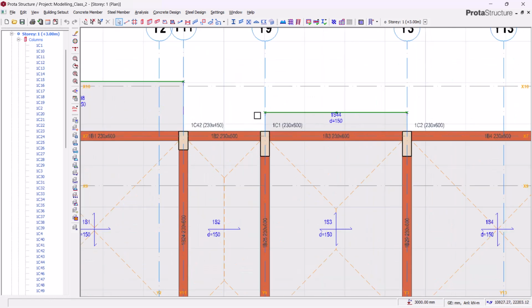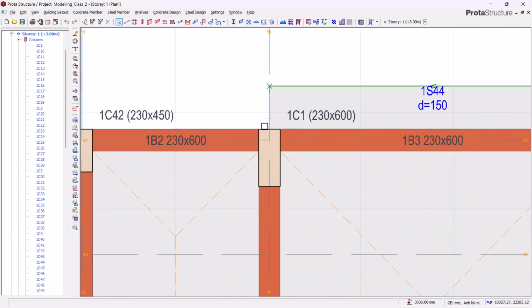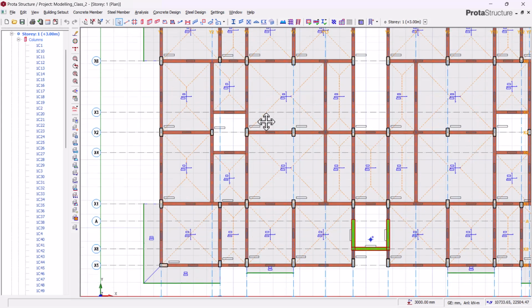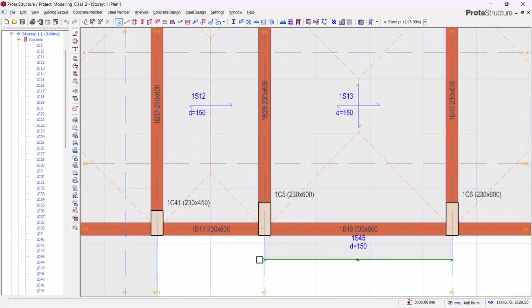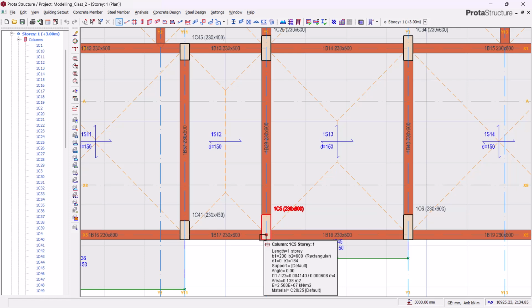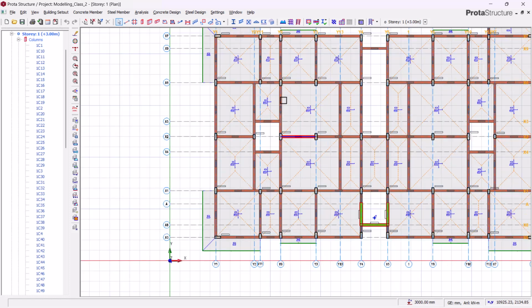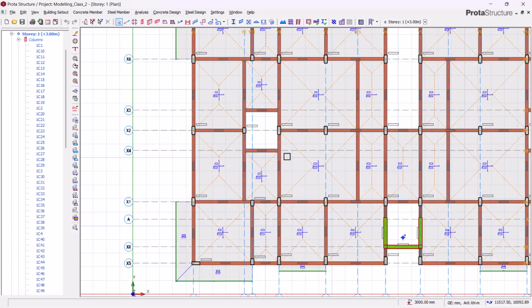Because during construction, if we run a line, if we get this point and we get this point, all right, and we also come to the last column, then we get this point and we also get this point, all right, we can run a builder's line all through from the top to the bottom. All right, and automatically our columns in between, which is this and this, we have to align to our builder's line. So it makes our construction processes easy by keeping them in a straight line.